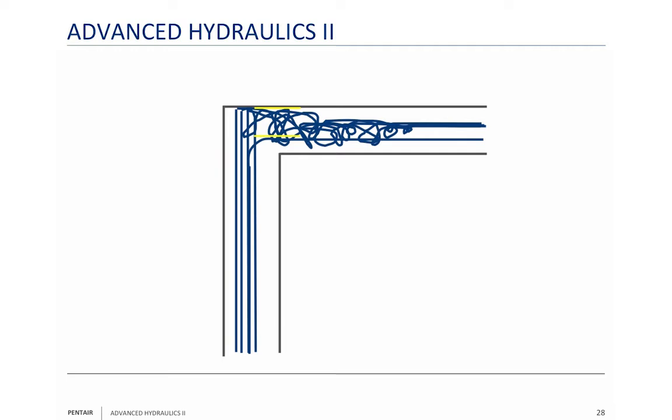So most of the water is going to go up and try and squeeze through that little area on top. Now, what does it mean? It means that the outside edge of the elbow is always going to have a high velocity, therefore lower pressure, whereas the inside edge of the elbow, where there's not so much water, is going to always have a low velocity, therefore a higher pressure.